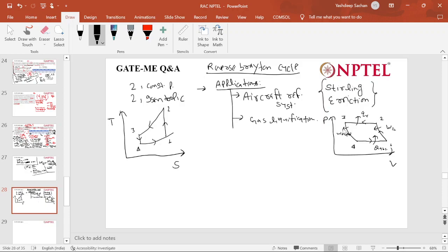Okay, one question I will ask. Here you are using a turbine, right? Yes, sir. And there in VCRS you are using a throttling valve. If you use a throttling valve here for the expansion, then what will happen? Question clear? Yes, sir. A large size of the valve is required. No. Why? Temperature gets reduced. Anyway, you want temperature reduction here, right?